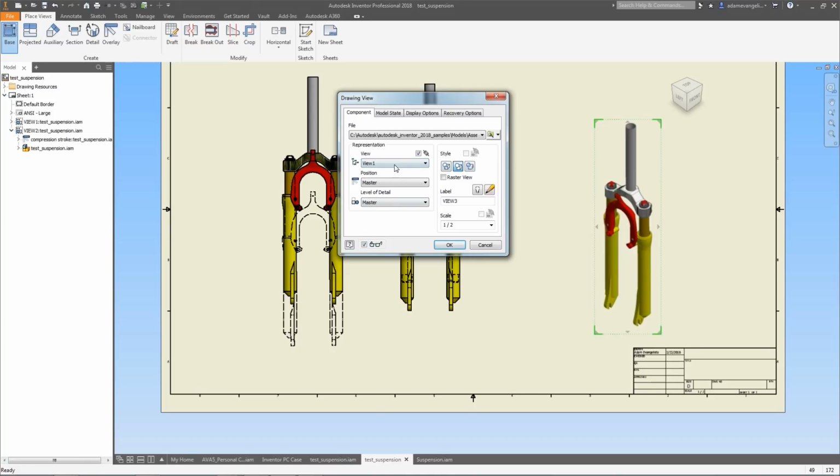And so it is good to note that I have my view over here, which is, I chose view intentionally, right? If I actually go to master, you'll notice that it gets grayed out, right? And so you'll remember that our default master view rep is locked, and you can't make changes to locked views essentially, right? So that's why if you don't see that box, maybe you're in master and you want to choose the appropriate view representation here.